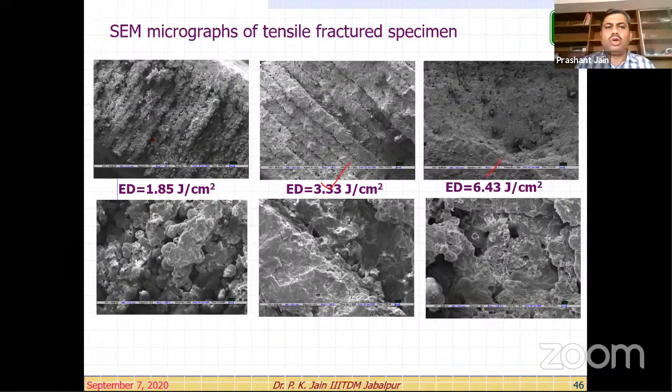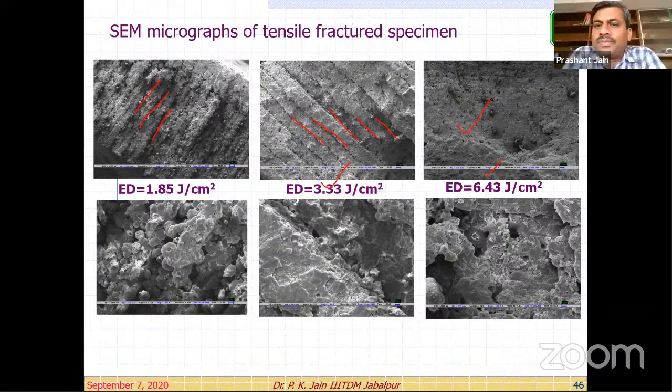So when it is less, you can clearly observe, just like a bread packet, a gap is there. The second is perfectly solidified, but still you can observe some gap between two layers. So the possibility is that delamination may occur. But when you increase further, this is completely solid. No delamination, no gap, no separate layers can be identified.